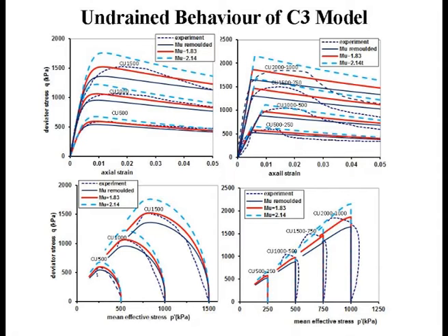But when you look at the stress path, the stress path is very telling, because in a heavily over consolidated soil, you will also have a peak and then coming down, right? But your stress path is going to the right. In this case, the stress path is going to the left. But it is not just going to the left and stopping here. It actually comes down like this. This is quite typical of structured material.